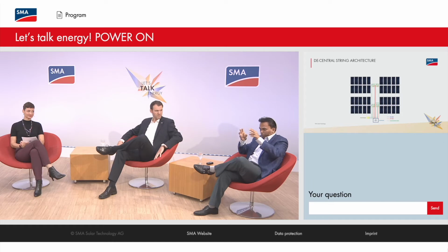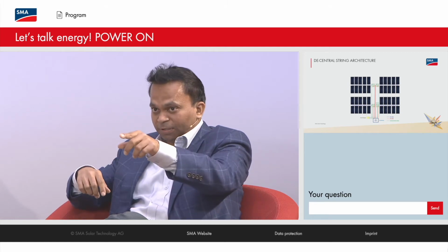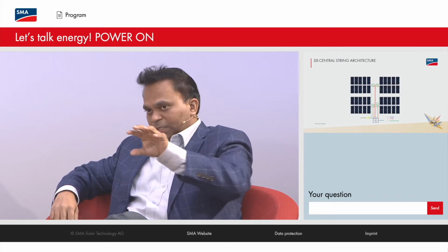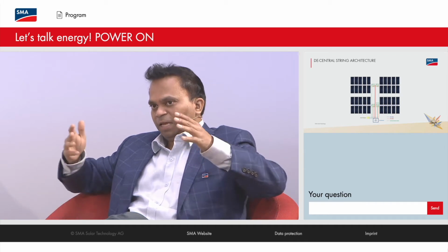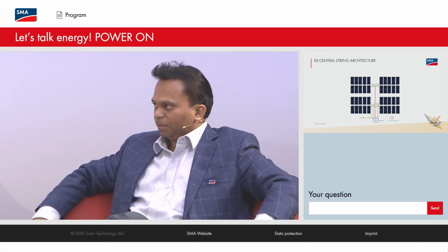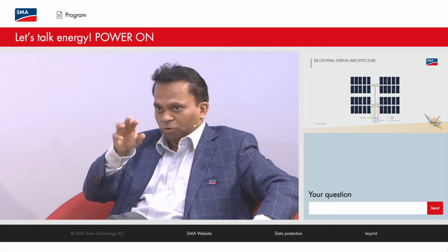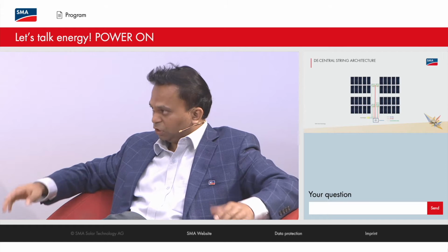They go to the inverter directly, and those inverters are distributed kilometers across the field. And then they bring the electricity in the form of alternating current in those red cables to the transformer, which is sitting at the bottom of this page. So this is the decentral architecture. It is called a decentral string because the inverters are distributed across the field. And the communication cables, as you can see, have to go a long way from outside to reach those inverters. So this is the decentral architecture.